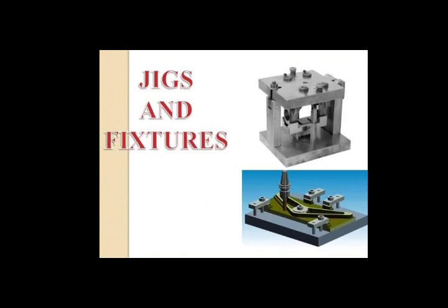Nesting provides locating surfaces on all sides of the workpiece, so it should be accurately manufactured and it involves more cost than other location systems. It is the most accurate locating device for profile locations. For cylindrical workpieces, a ring nest is commonly used. A full nest completely encloses the workpiece, whereas a partial nest encloses only a part of the workpiece.